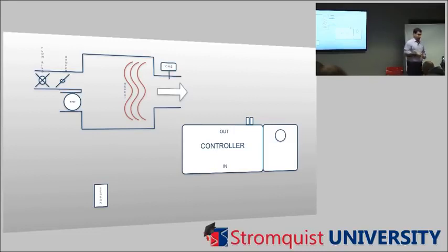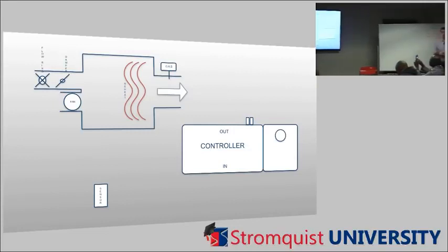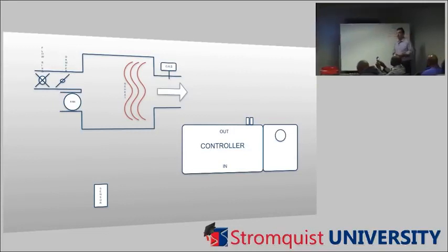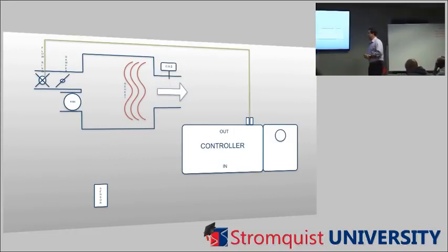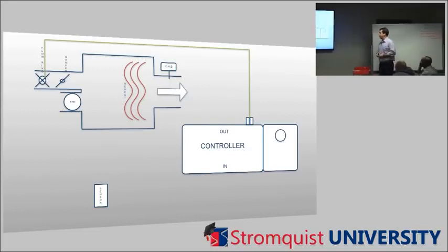So let's wire this up. Now, in my brain, what I had you guys doing was kind of helping me out, but I can see by the enthusiasm that you've shown me this morning, I'm not going to have a whole lot of volunteers. So I'm going to give you the first one. The flow ring, we talked about that pressure sensor. You've got little pressure tubes that come off of that flow ring and go into those two little red things I showed you on the Spider. All right, so then that damper, do you guys think that's going to be an input or an output?